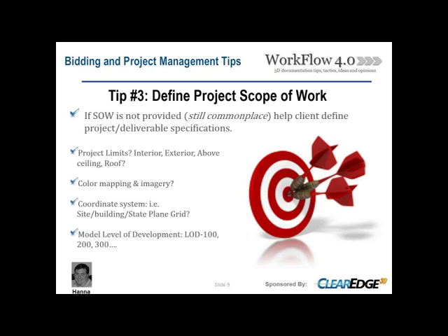And then furthermore, try to understand the bigger picture for your client. Is it important to get the point cloud on a known coordinate system, whether that be state plane grid, building grid, site plan coordinates? This way, knowing that from the get-go, understanding the overall project goals is going to enable that client to work with this data more effectively through the project lifecycle.